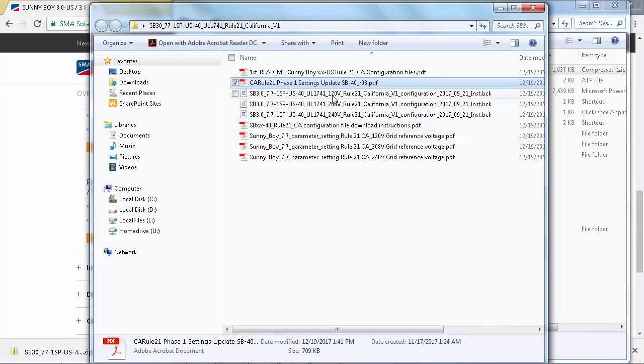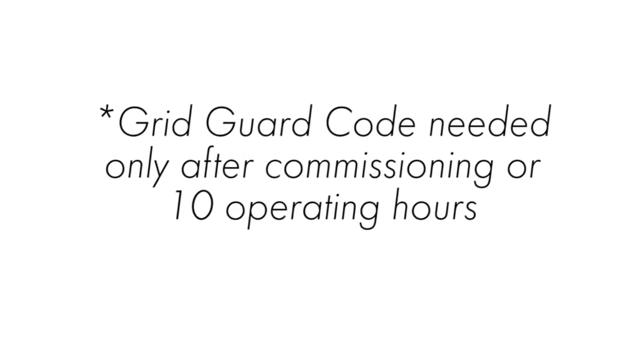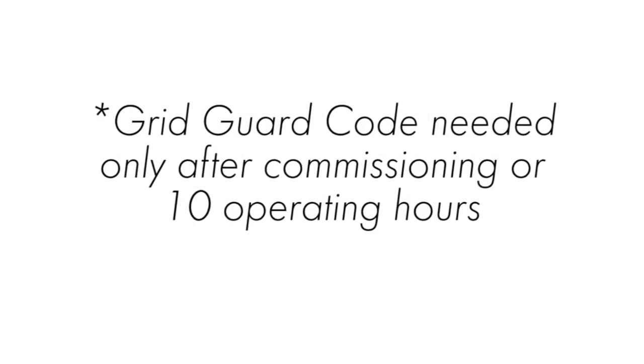Please note that there are 3 parameter files. For split-phase residential 240 volt, 120 volt, or 208 volt Y utility connections, the 120 volt file must be used. Only use the 240 volt file for 240 delta service, and only use the 208 volt file for 208 delta service.